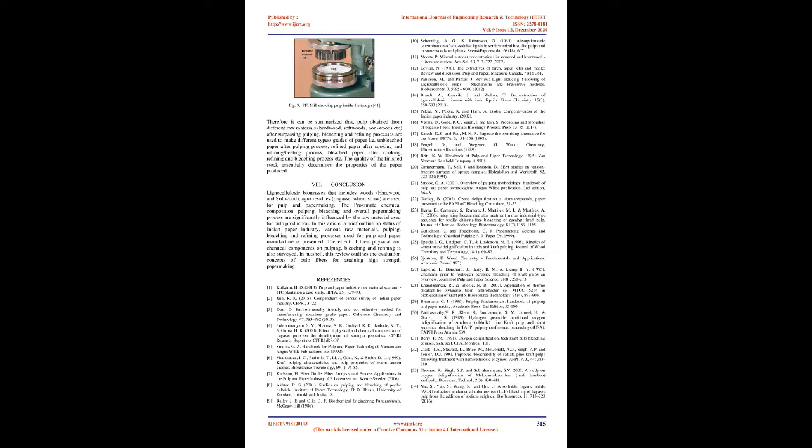The chemical pretreatment of the chips permits sulfonation of lignin, which causes swelling and weakening of the lignin matrix and consequently separation of fibers from the wood, resulting in a higher and longer fiber content, and a much lower fines content than TMP. The CTMP pulps show good strength properties and higher brightness before bleaching. CTMP is best suited for absorbent grades and food packaging. The pulps are weaker than chemical pulps, but cheaper to produce, about 50% of the cost of chemical pulp.